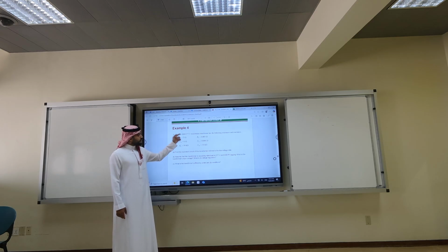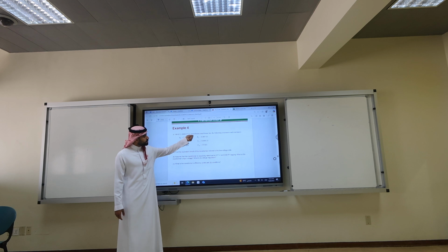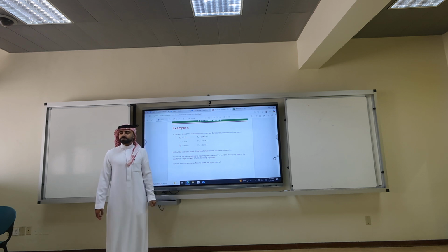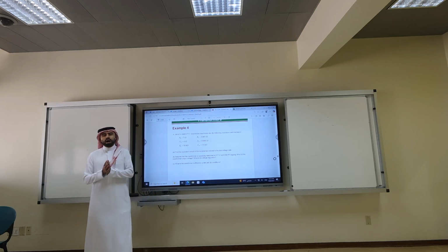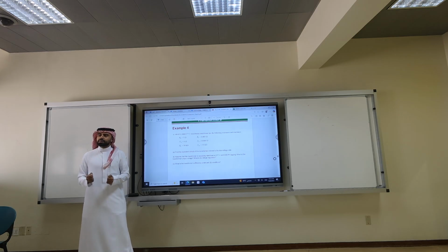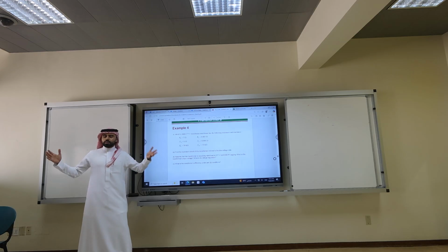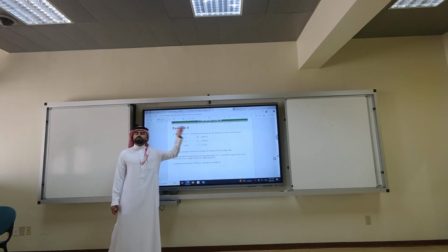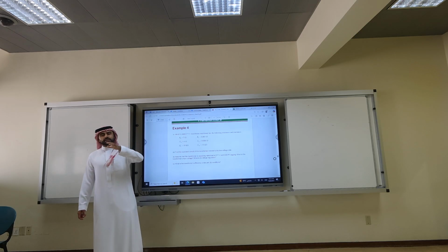Rated for the transformer because it connects to the distribution transformer. Is it single phase or three phase? Single phase. Why? Because for transformers, unless I tell you it's a three-phase transformer, it is usually a single-phase transformer. Big transformers are three-phase. Distribution transformers are single-phase. Some you might see as three-phase distribution transformers. Again, you see everything in the field.